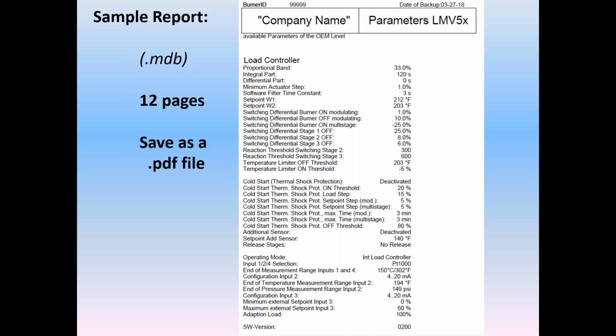This is a great thing to give to your customer to show the professional level which you have of all the commissioning and all of the data on your LMV system. It also serves as a discouragement from them to let any of their operators or users go in there and change parameters. This usually ends up in a nuisance call coming later. Hey, my sensor doesn't work. We didn't do anything. By presenting this to your customer, you have full documentation of everything that was done on the unit and how it was configured when you left the site.